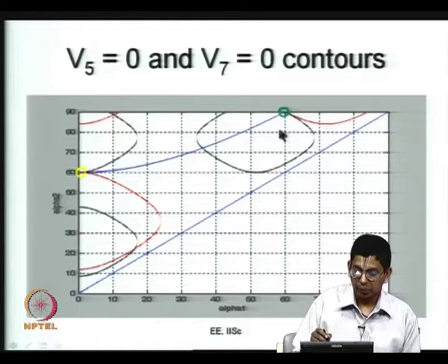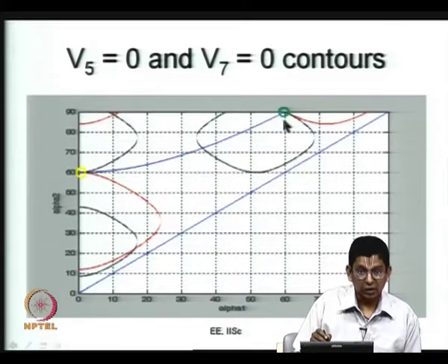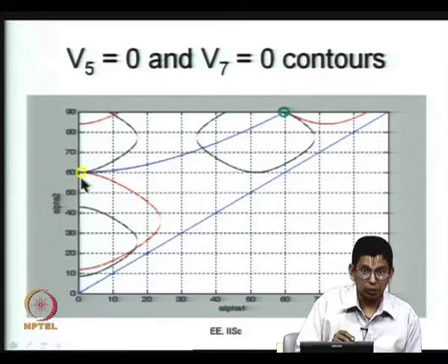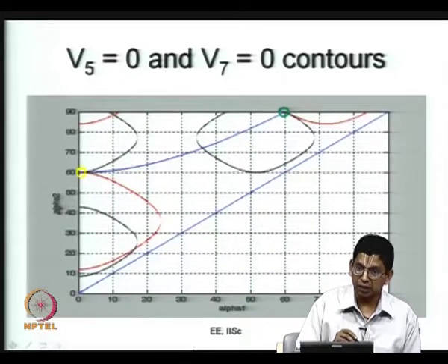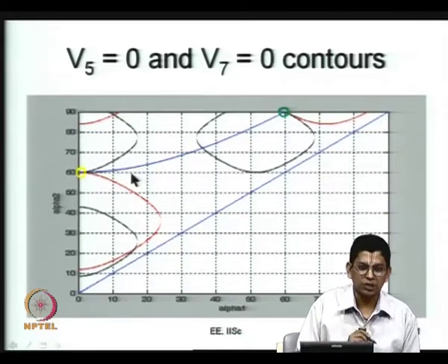because the waveform is a third harmonic square wave here and it is also a third harmonic square wave, as I told you in a previous lecture. So, the 5th, 7th, 11th, 13th harmonics do not exist. Not only the 5th and 7th which are shown here, 11th and 13th also do not exist. So, both are equally good options now.